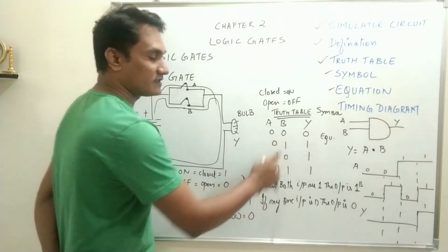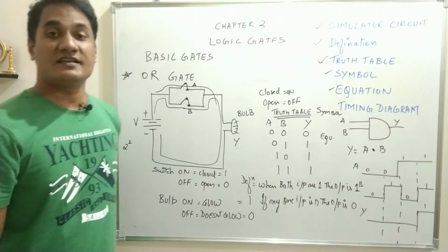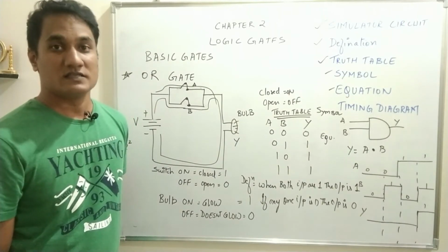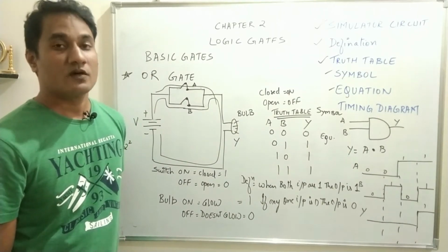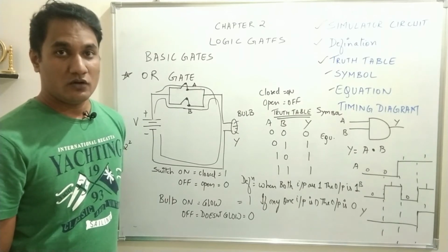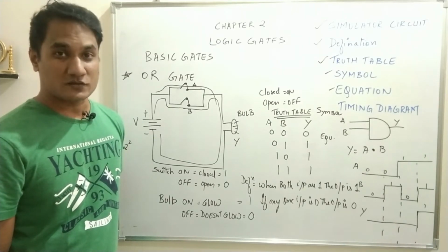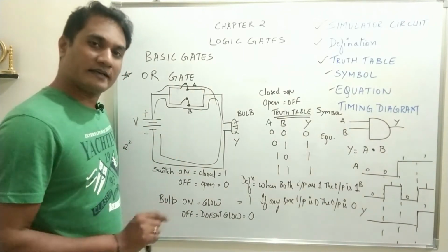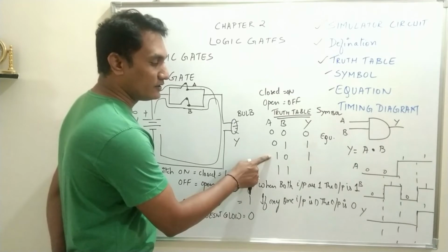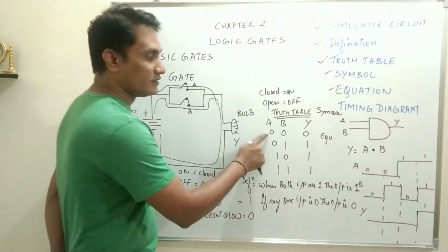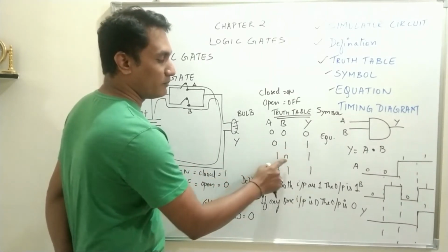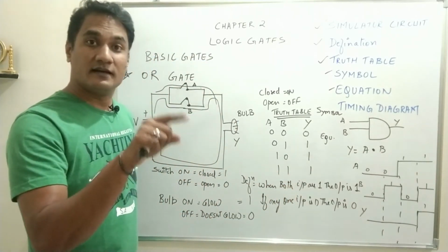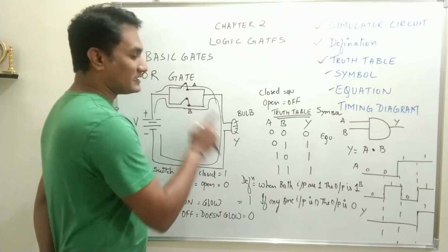And what you can see is, of course, we have done the addition of binary numbers, binary arithmetic. 0 plus 0, 0; 0 plus 1, 1; 1 plus 0, 1; and 1 plus 1 we consider to be 10. Now if you remember those addition rules and compare them with the truth table of the OR gate, 0 plus 0, 0; 0 plus 1, 1; 1 plus 0, 1; but 1 plus 1 in addition is 10, but in OR logic it is 1.